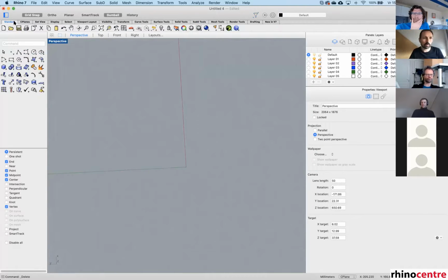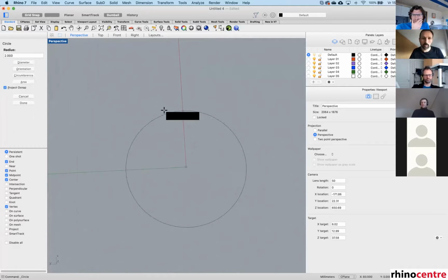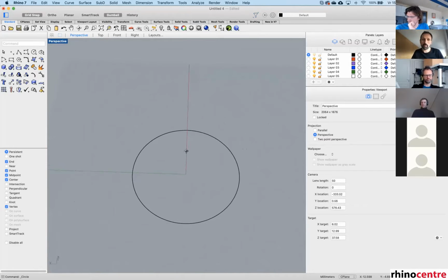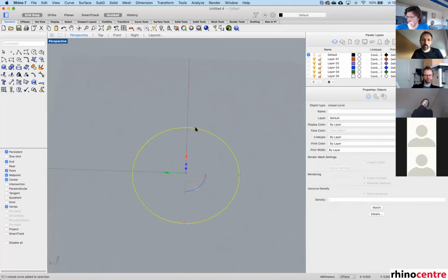If you want to make your subdivision surface fit to a circular object, then you need a sufficient amount of control points based on your document tolerance. I often work with 1/1000th of a unit as tolerance.